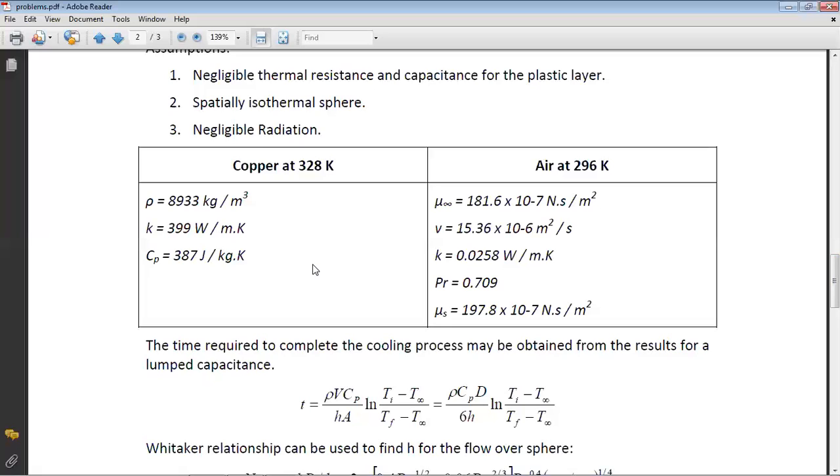Now in page number 2, you have copper, pure. You can have the values of density, thermal diffusivity, specific heat, as well as thermal conductivity. If you go by the value in page number 2 for copper, the value of density is 8954, the value of specific heat is 383, and the value of thermal conductivity is 386. With little variation, these values are taken. There could be pure copper, there could be some alloy. Little variation is acceptable.